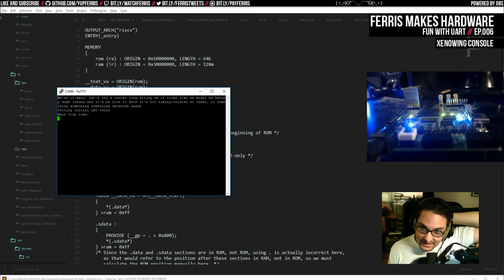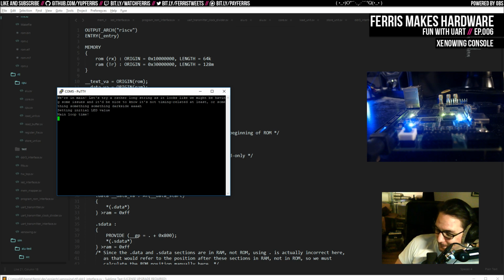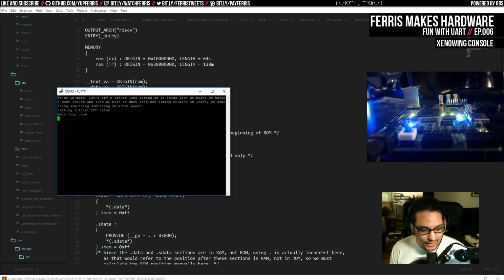So I'm thinking that if we can send over new ROM, I could build in a little hardware unit that, whenever stuff comes in on that RX line, just holds the processor in a reset state, and then goes and replaces the ROM, because it's really just RAM with no write port right now. And I can just add the write port to something else and just not give the CPU access to that. Anyway, then it would reset the CPU and hold it in that state and replace the whole ROM, and then reset the CPU is what I'm thinking. And what would be really cool about that is that it would allow us to, again, reload code live. Especially when doing the HDMI transmitter stuff, I think that'll be really useful.